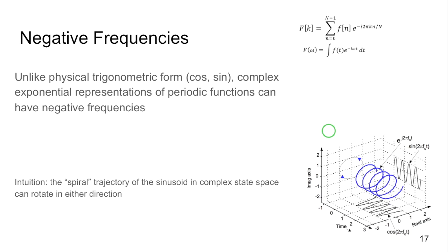And if we want a geometric interpretation of that negative sign, one way to look at it is if we go back to this phase plot. Before, when we had a positive frequency signal, this spiral was traveling counterclockwise through time. For a negative frequency, it could be said that the spiral is traveling clockwise, in the opposite direction. And that's where our negative frequency comes from.